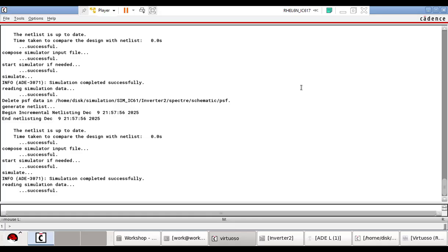Okay, see, the use of this process analysis is that you get the minimum and maximum value of your parameters of your particular device. If you are going to work on power and delay only, you will get the value of power and delay. Suppose you are working on analog, you find values of transconductance or other values. All these values you can use as a specification of your device, because you have done the process corner simulation.